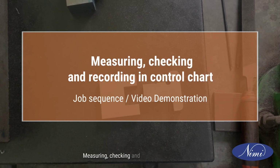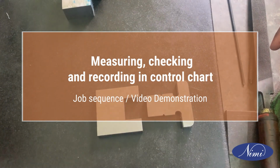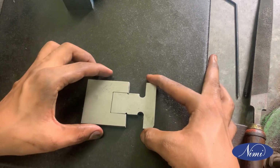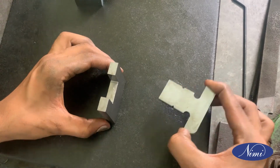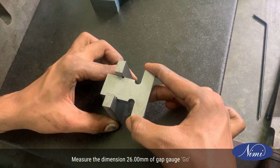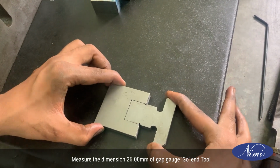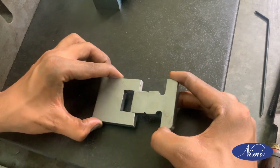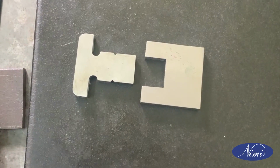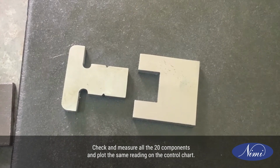Topic 6. Measuring, checking and recording in control chart. Measure the dimension 26.00 mm of gap gauge go end tool. Check and measure all the 20 components and plot the same reading on the control chart.